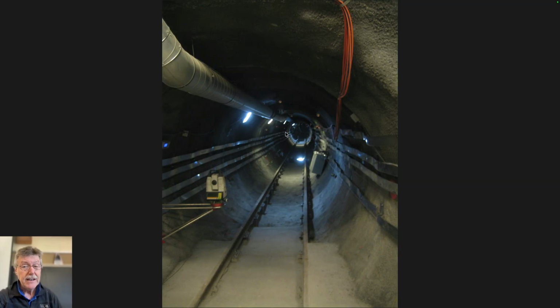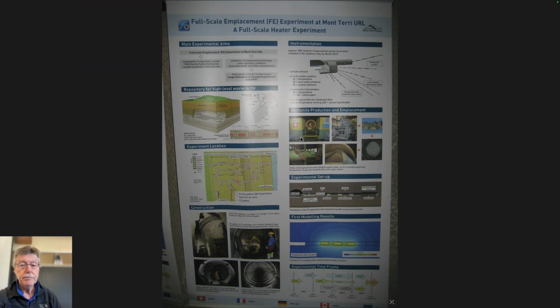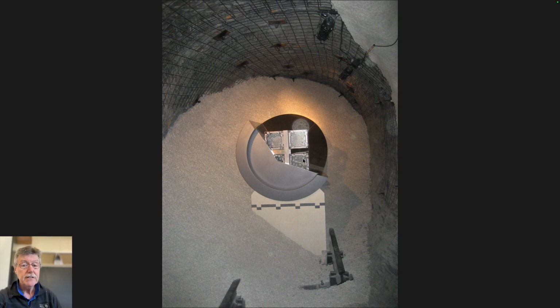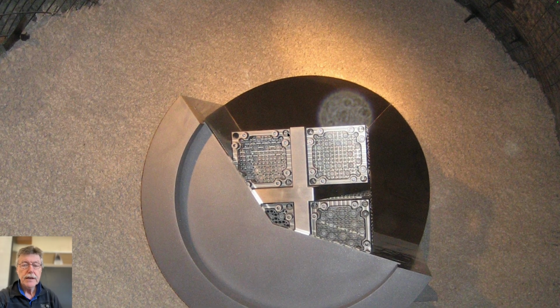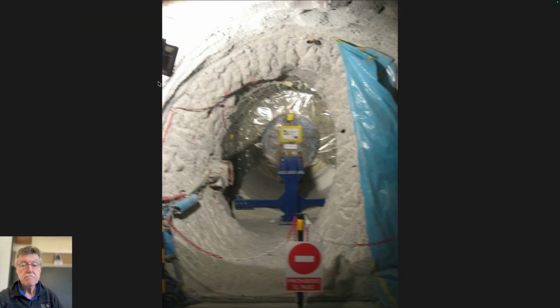An experiment at the end of one of these little tunnels to look at, some of these experiments were looking at how well bentonite sealed up heated containers and stopping their products escaping by going along a little tunnel. This kind of idea, this is a model of exactly what it was, rather than the actual thing, but it is underground. So fuel rods in a container, placed within a canister, placed within bentonite underground. The idea being that the bentonite, if these canisters break, then the bentonite is highly sorbing, so it soaks up radionuclides and doesn't really allow water to flow through it.